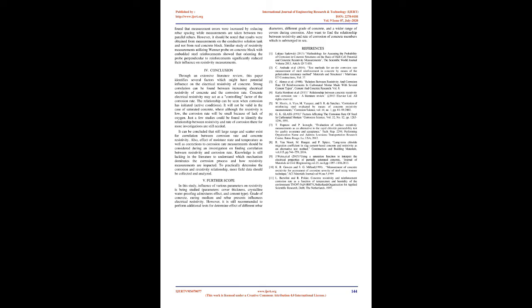B. Effect of curing condition. Weiss et al. [9] performed a numerical study that attempted to simulate a mortar with a water to cement ratio of 0.42 with three curing conditions: A. Sealed during curing and testing. B. Sealed during curing and saturated during testing, and C. Saturated during curing and testing. It was concluded that the specimen that was sealed during both curing and testing had the highest resistivity whereas the sample that was sealed during curing and saturated at the time of testing had the lowest resistivity.